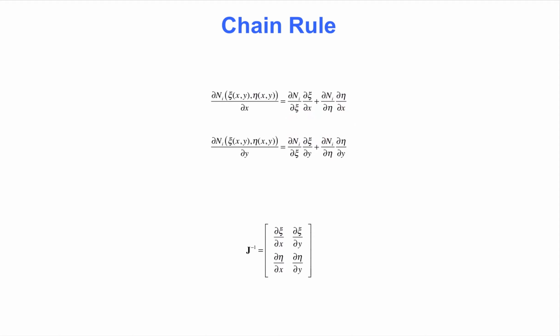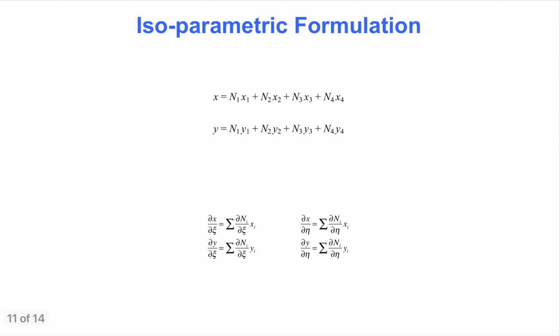The differentiation with respect to y follows the same pattern. The derivatives d xi dx, etc. are the inverse of the Jacobian entries we introduced on the previous slide. For that reason, the derivatives needed on this slide are taken directly from the inverse of the Jacobian matrix, shown below. We have not yet calculated the components of the Jacobian matrix, and that is addressed on the next slide.